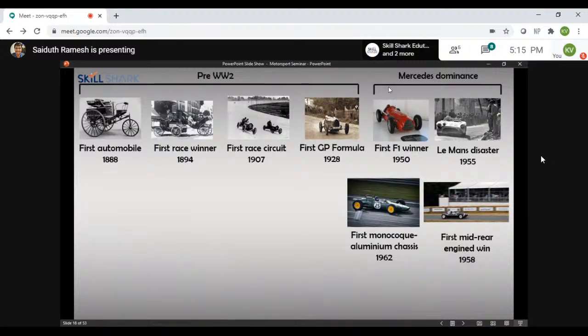Now, generally chassis are either tubular framed or monocoque. Tubular frame chassis have tubes that are welded together to create a frame. Monocoque chassis are almost 3 times stiffer, and they also weigh about half as much. So these were really efficient, and this was basically a championship winning car and won almost 14 Grand Prix.